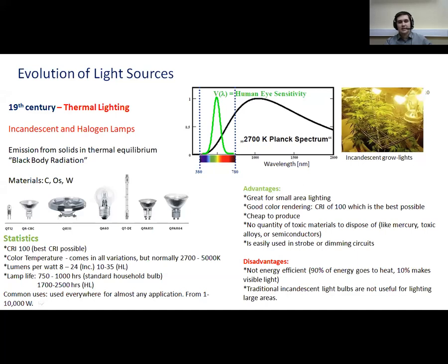As an alternative, halogen lamps are applied, with efficacies up to some 20 lumens per watt. A halogen lamp contains a halogen, like for example iodine, bromine, chlorine, and something like that, in addition to the normal gas filling. The combination allows an increase in the lifetime of the lamp due to the halogen cycle. As usual, this type of lamp is used in compact reflectors.